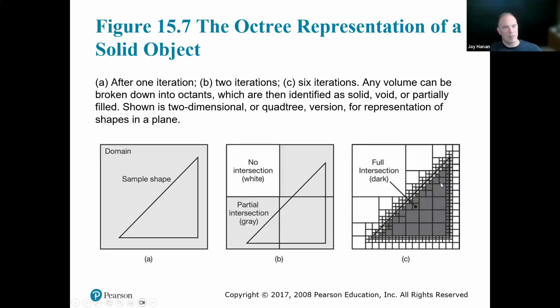And you just keep dividing until you get enough information to determine the edge, in this case, for the triangle. And you can see you have most refinement around where the change is most abrupt, which is these corners and the ends, and then you can deal with larger squares here on the interior. In fact, you don't really need these four. You could make that also larger.